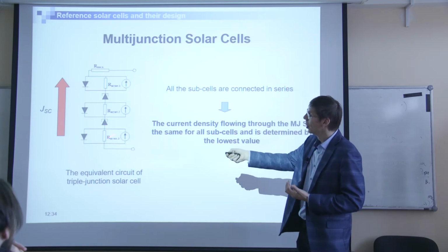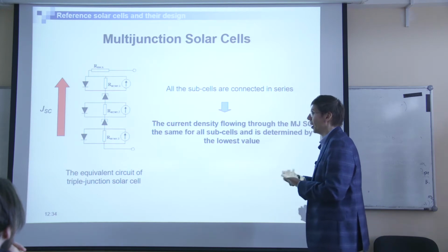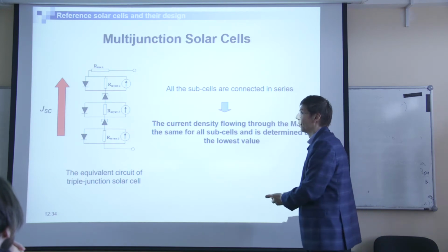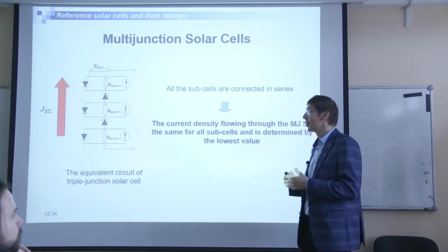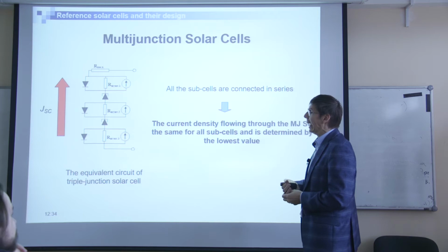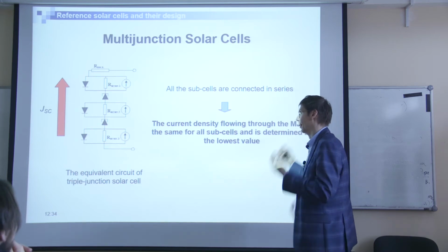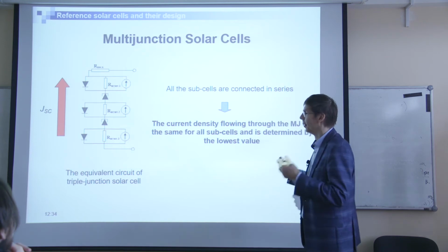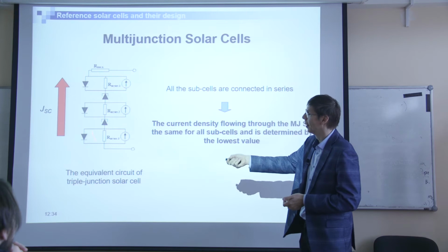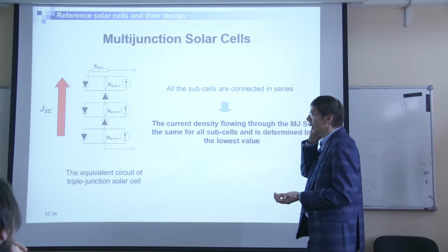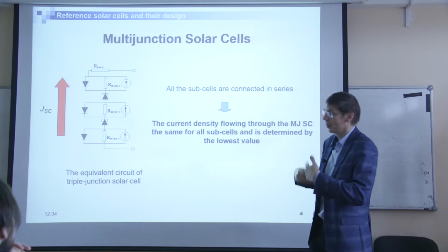So the bottom germanium subcell would get much less light compared to the normal case for normal solar spectrum. And in this case, if you have, for example, half of the light, you have half of the current, and you would have half of the total current and your efficiency would be half.